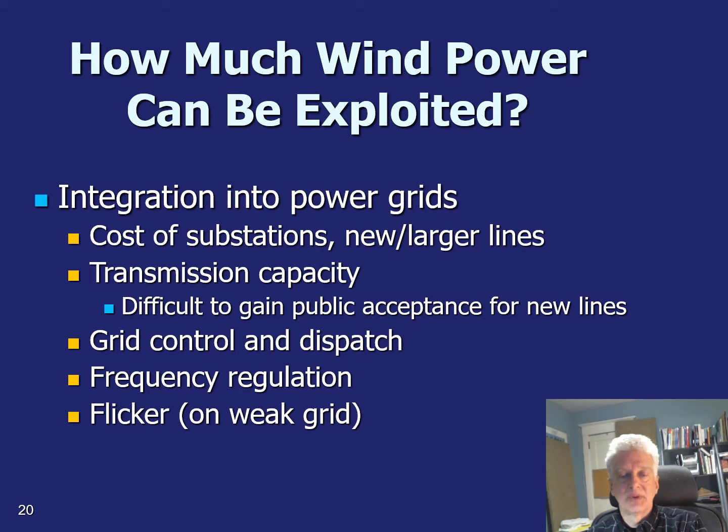Once you have the permission to do this, then you would need operating controls that will make the new sources work smoothly with the existing power grid. So power grid management, that has a whole technique, a whole science for managing the sources that are there, controlling their frequency. And when you're on, let's say, a remote location where the grid is just a single line that both feeds residents there and now is taking your wind, you might be introducing a lot of power, and you can actually cause people's lights to flicker. That's come up in the past.